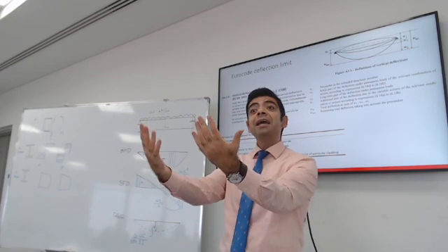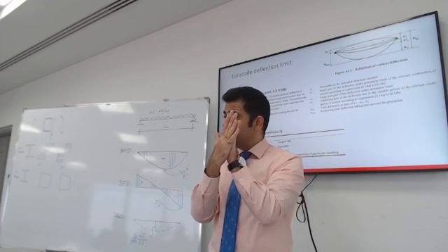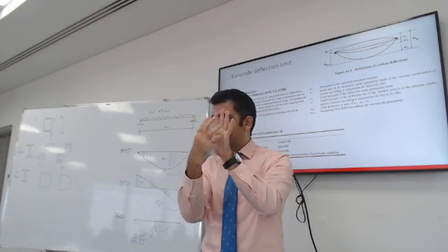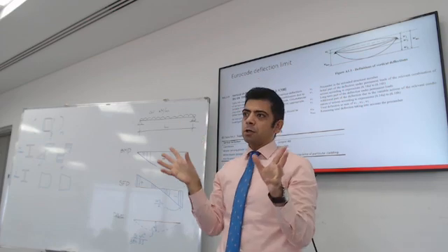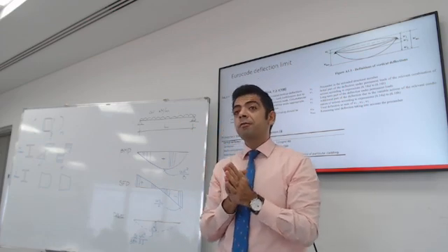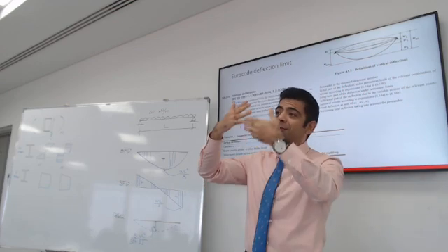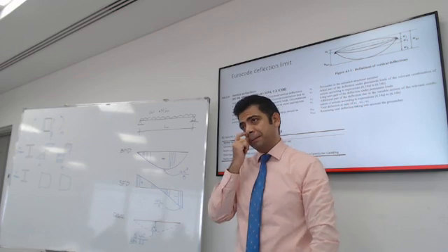When the wind hits the building, it hits the window, and the window needs to be able to support itself to transfer the load to the structure. That's the only structural function of the window. Other than that, I'm not relying on the window to transfer the load to the foundation.